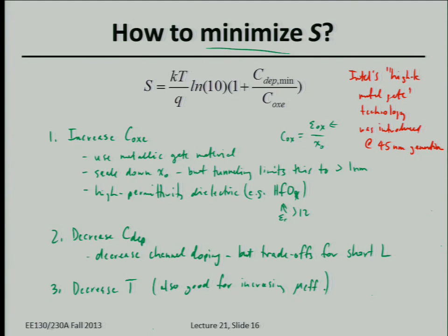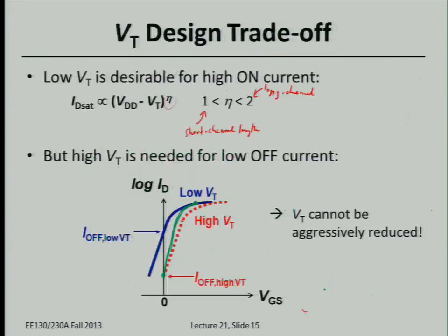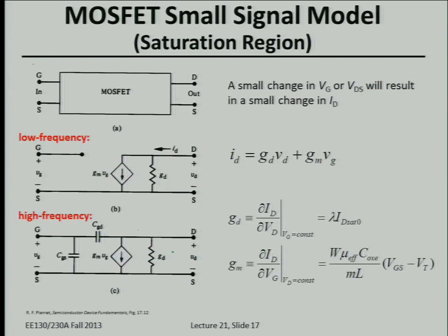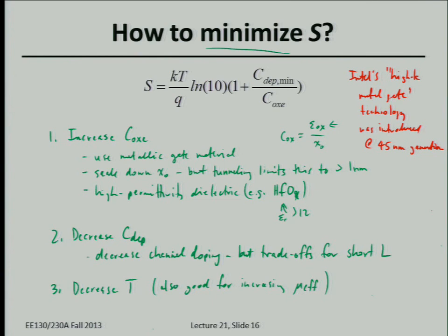So overall, what was the purpose for getting steeper subthreshold swing? Is to lower power consumption, right? So you can have lower off-state leakage for, let's say, a given on-state current. Okay, but if you need to apply energy to cool down your circuit, then overall, it's probably not likely that you're going to save power overall. Okay, so that's it for digital logic.